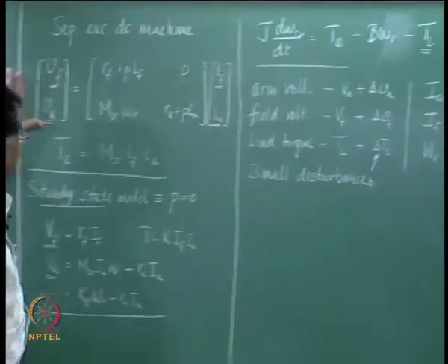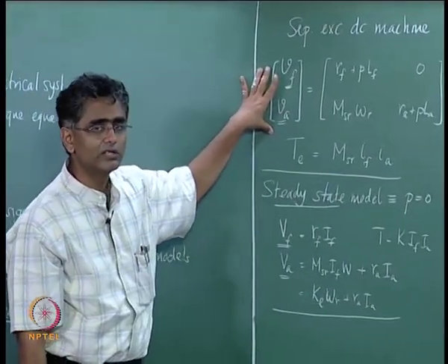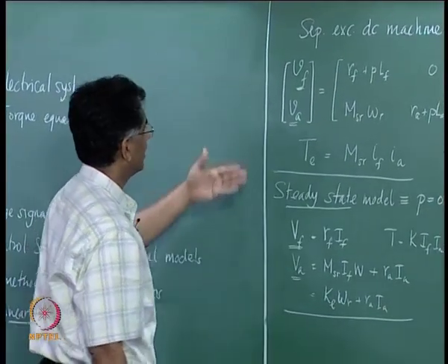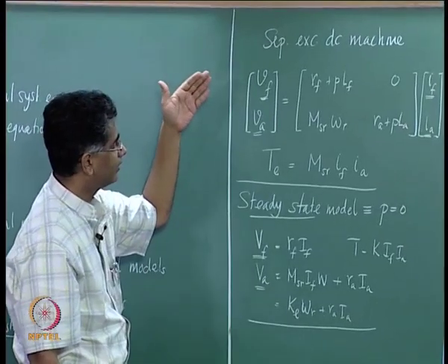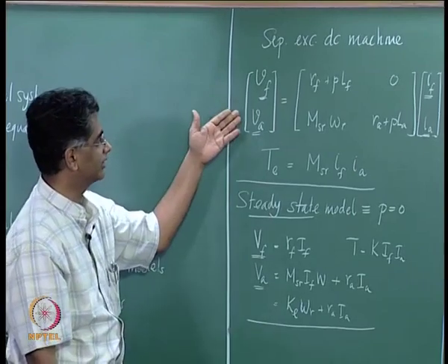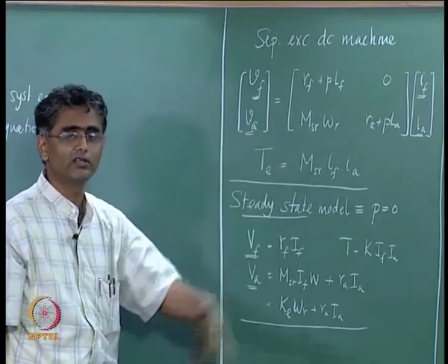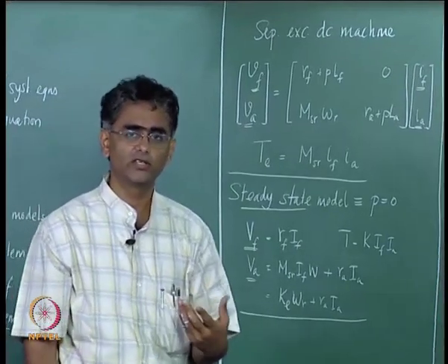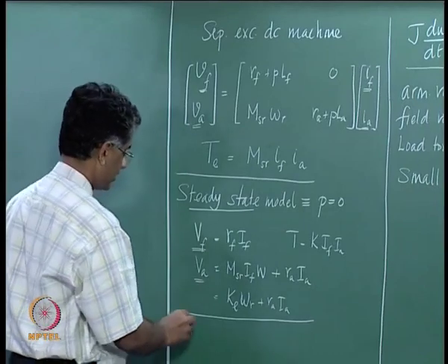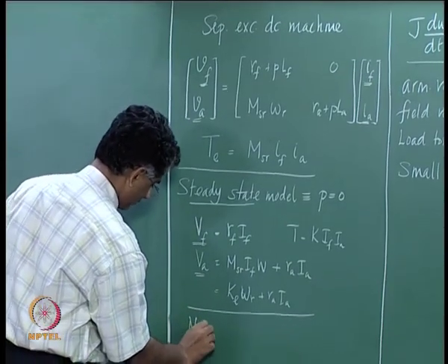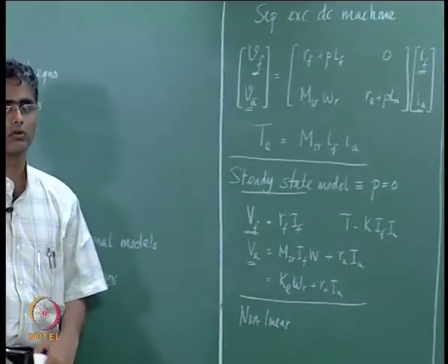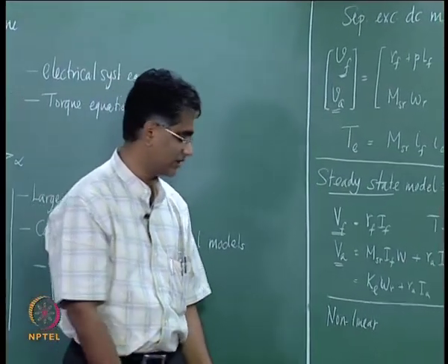Now, these equations that we have derived are applicable under all situations. These are large signal representations of the machine, or arbitrary signal representations, and therefore they are valid whether the signals are large or small. The only thing is this equation is inherently non-linear, and therefore we would like to have a linearized representation.